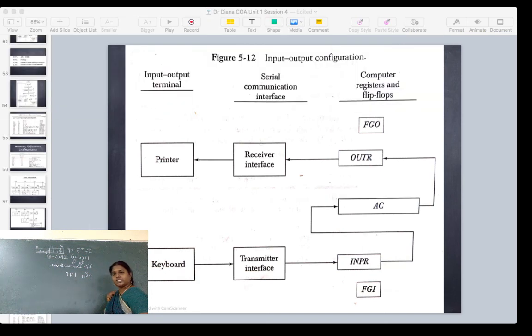So I have to read something inside the accumulator. So the accumulator should receive data from which register? The input register. Now I am going to assume that the interface has already started working, and when I am executing this at time cycle T3, my data is available at the input register.